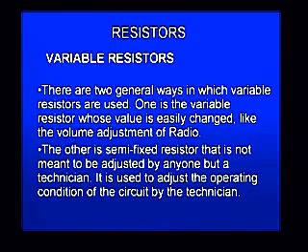There are other semi-fixed resistors that are not meant to be adjusted by the user, but by a well-trained technician. It is usually to adjust the operating condition of a circuit. So it will not be accessible to the user, but will be inside the circuit. The technician will set it up, slightly vary it to the preferred value, and set it at that stage. Nobody will be able to change it beyond that. These are called preset variable resistors.